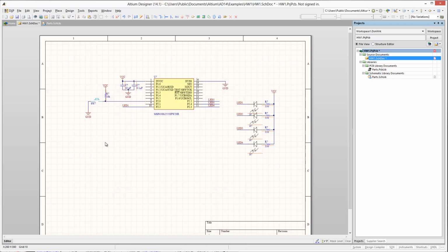And this is why we really place bypass capacitors right at the power pin. This way we know, okay, these two capacitors have to be physically close to this power pin, and not just have them on VCC power. We could have them just down here like this, but that doesn't give you an idea of where you actually want to place these capacitors, because the power network can be fairly large. So we want to have them physically located close to these pins.